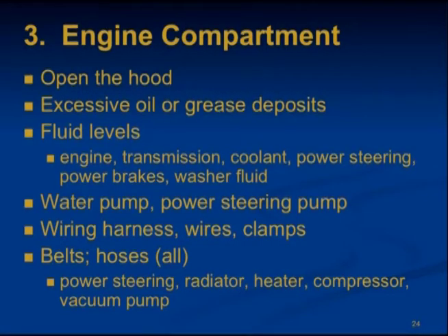Check all belts. Check by twisting, turning, and looking for cracks or fraying. Check for looseness. There should be no more than 3/4 inch play in the belts. Check all hoses by twisting, turning, pinching, squeezing, feeling, and looking. And check for contact with other parts, chipping and cracking, including the radiator, heater, and compressor vacuum pump hoses.